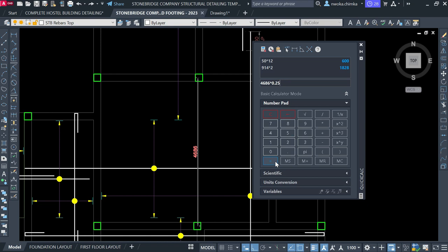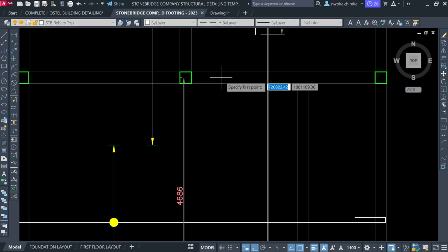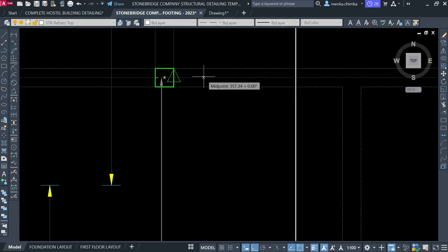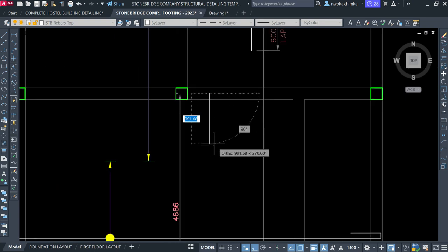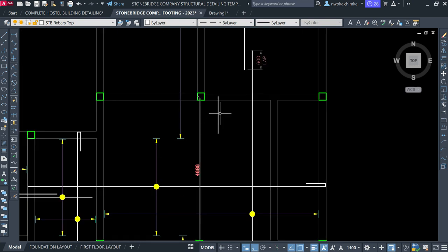Okay, as I go here right now, click equals, that gives me 1171. So I'll just say approximately 1172 length, which is where the top bar is meant to occupy. Now I'll press enter, trace from the middle here, and type the value 1172. Yes, that was what we got, and press enter. So this now becomes my main top bar.